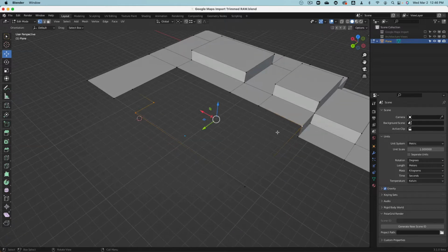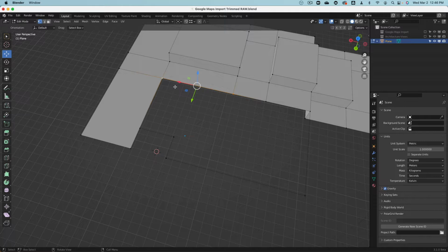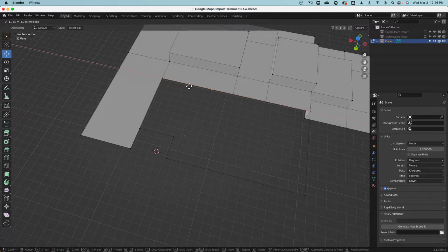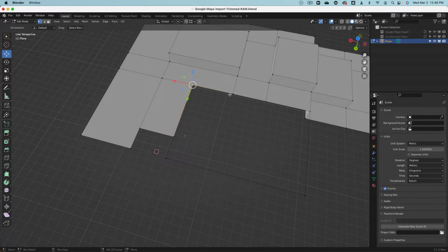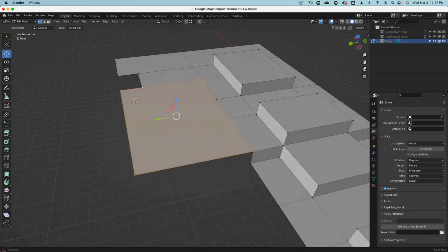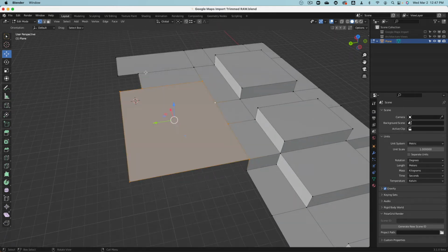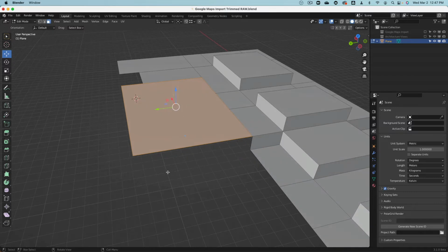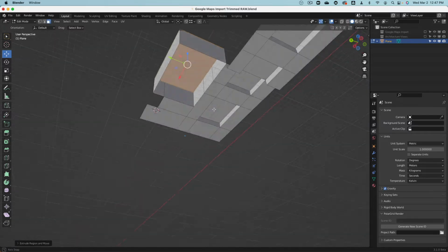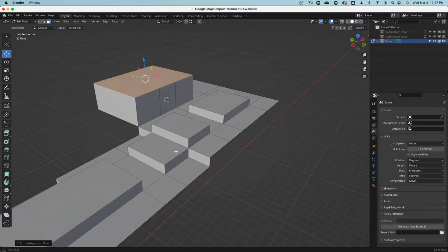So these are walls that will go up. This here actually will go to there. So I need also here to have a point to connect this to. So select this edge, subdivide. This point I move along X, hold control and snap. Yeah, and then click, click, click, fill, click, click, click, click, click, click, fill. Oh, I forgot this point, fill there. And then this whole thing, E, we extrude up there. See? Beautiful.